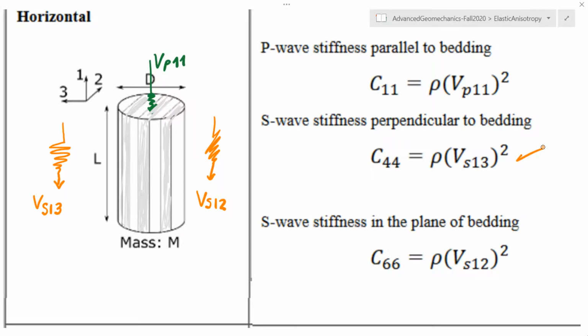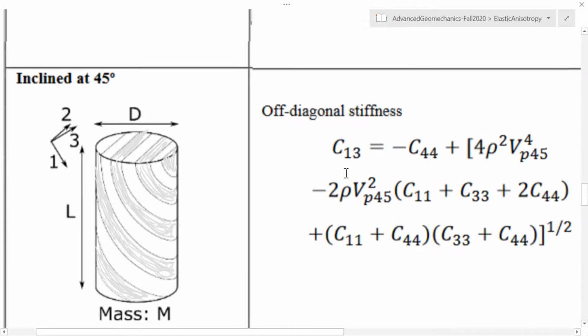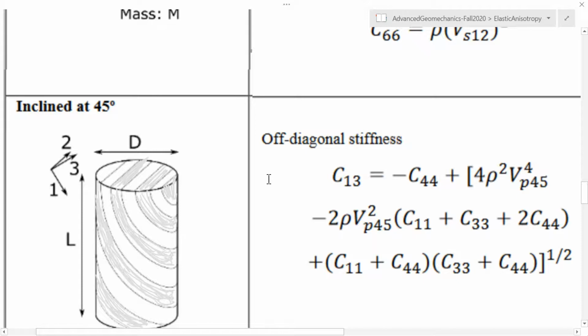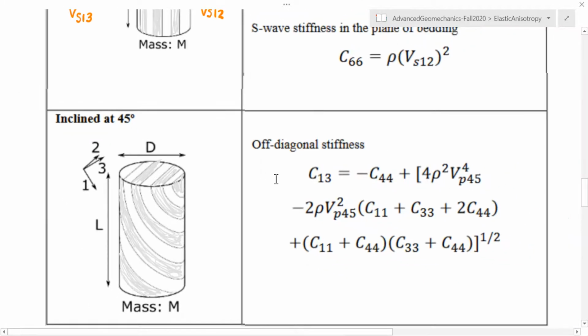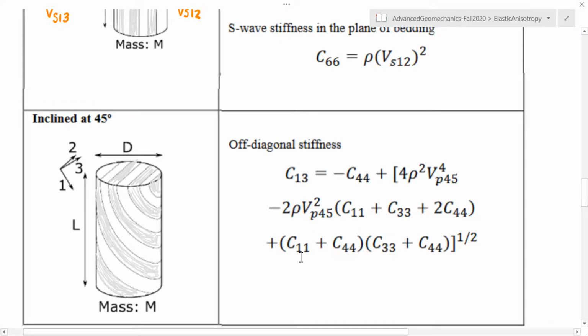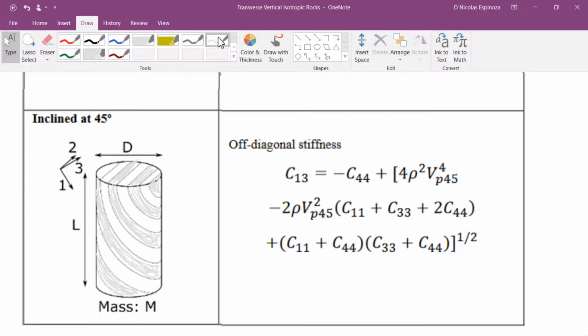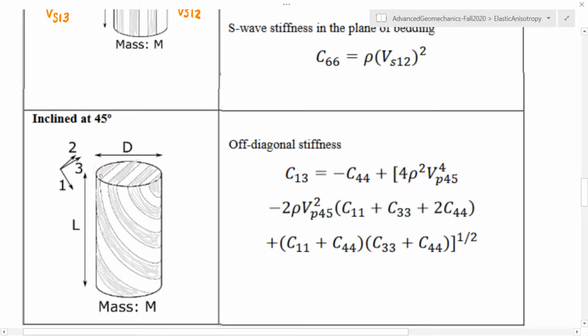With the dynamic method, I'm trying to find a good word to say this, but I would say it's a better representation or a better case to use now a 45-degree oriented sample, because the deformations are very small and the changes of stress are very small, such that it's very unlikely that we're going to reactivate or fail in shear some of these planes.